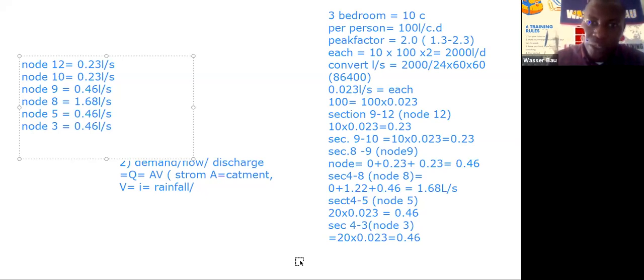So we'll go back to our drawing. Yes, there are houses. There are about 1, 2, 3, 4, 5. And in our characteristics way, we'll say there are also meant to be houses here, but they are unbuilt. That is about talking about the future that I discussed yesterday. So let's assume there are another 10 houses again. There are another 5 houses on the opposite direction, making 10 houses. So that means the base demand for node 4 is already 10 houses.